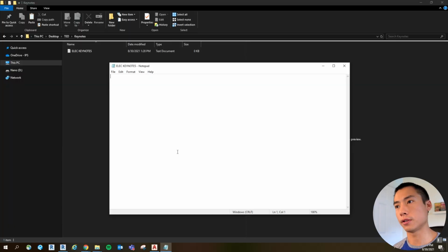Revit reads a specific format, and you'll have to follow this format, otherwise your keynotes won't show up in the software. To start, you basically need a defining initial. You can start with a P and then press tab, then type out the description for that letter. So this will be power. Then you can press enter, do another one like L for lighting, S for system, and ST for site. I believe you can use as many letters as you want, but the problem with using multiple letters is that it starts coming out of the keynote symbol.